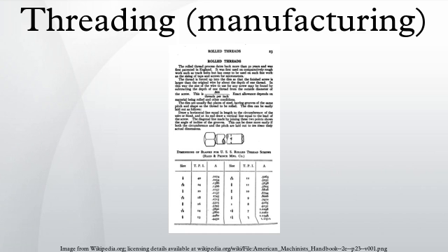The coordination of various machine elements including lead screw, slide rest, and change gears was the technological advance that allowed the invention of the screw cutting lathe, which was the origin of single-point threading as we know it today. Today engine lathes and CNC lathes are the commonly used machines for single-point threading. On CNC machines, the process is quick and easy due to the machine's ability to constantly track the relationship of the tool position and spindle position. CNC software includes canned cycles, that is, pre-programmed subroutines, that obviate the manual programming of a single-point threading cycle. Parameters are entered, and the machine does the rest.